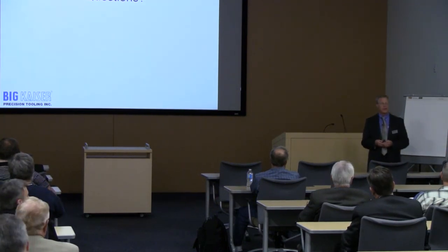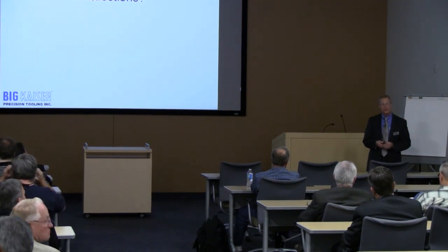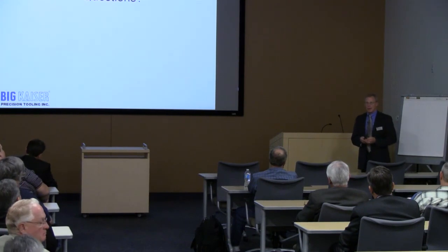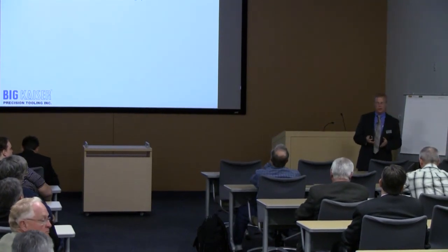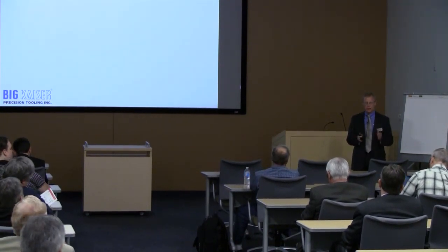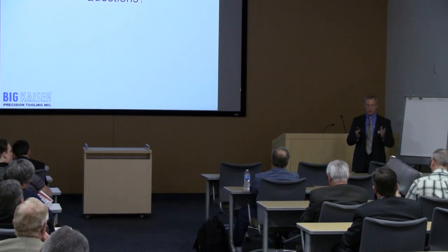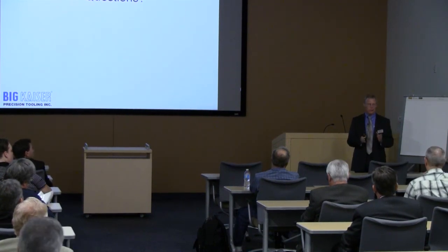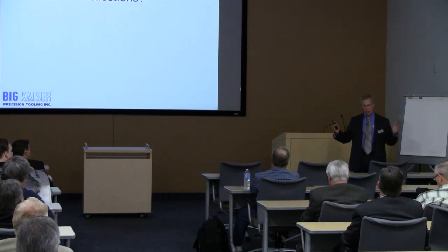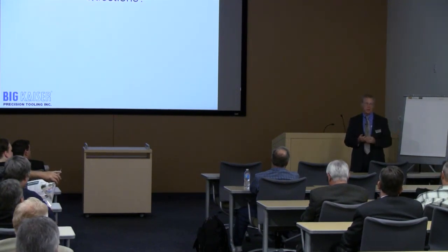Yes, sir. How would you say that this business with the Big Plus 40 compares to the standard 50? There have been statements out there that if I take a 40 taper machine with Big Plus, I can get nearly the same performance of a 50. In certain cutting conditions, I would agree to that statement, but overall, you'll never be able to take a 40 taper machine and equal the cutting capacity and torque, moments, lengths of what a 50 taper can do.